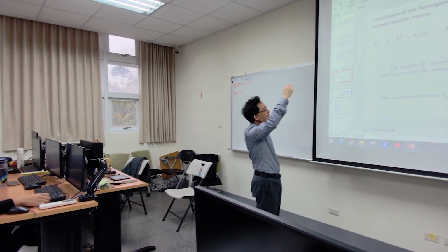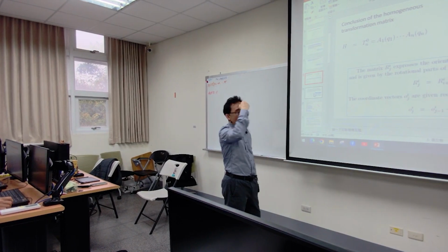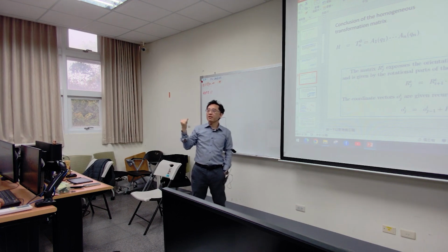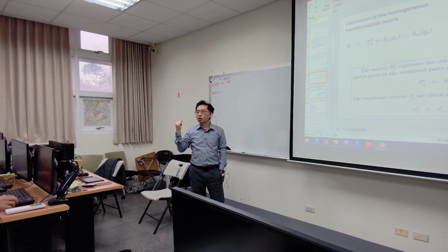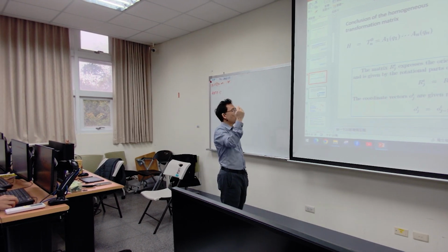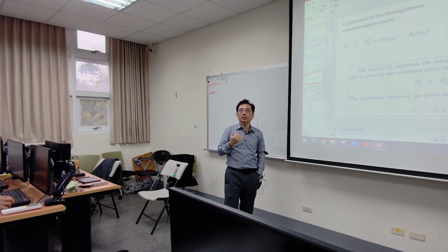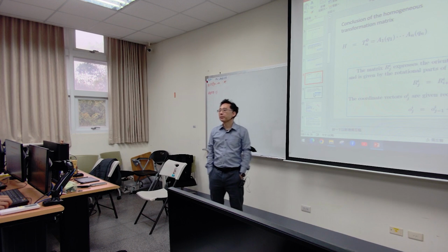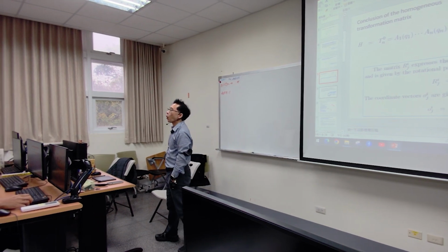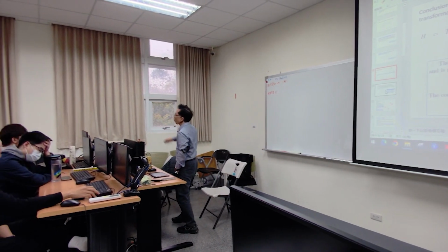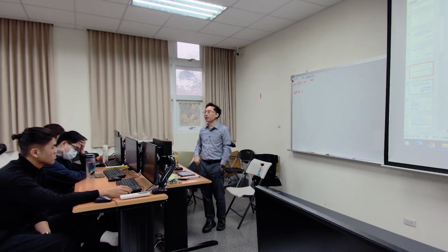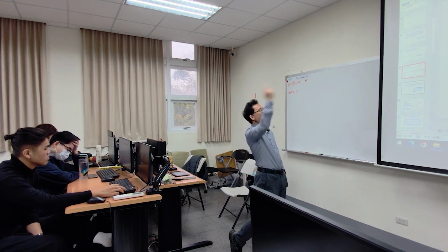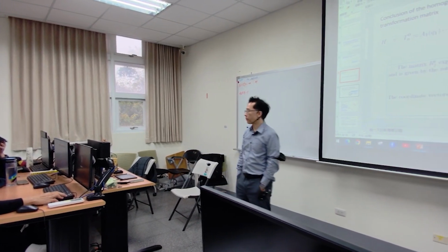In this example, if I assume my n is 6, the last end-effector is the 6th joint: 1, 2, 3, 4, 5, 6. Then I refer back to 0, the original one. The global frame is called 0. So I refer the 6th frame to the original one, called 0.